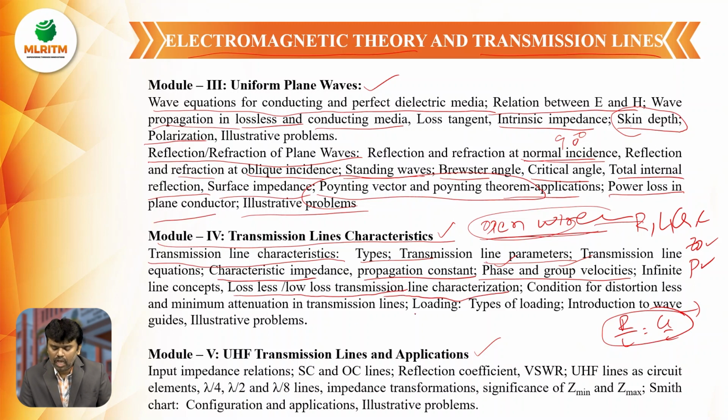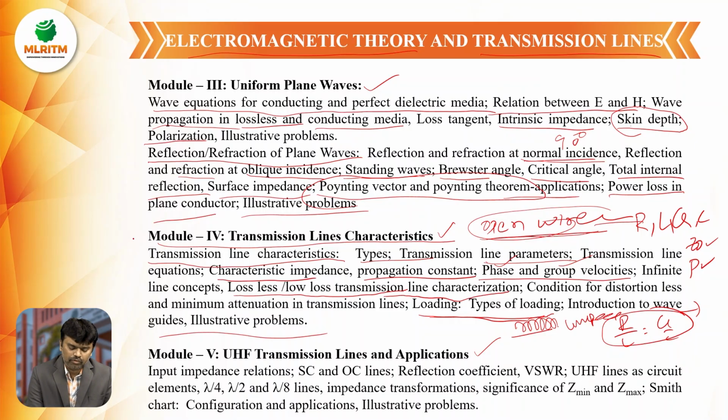How the transmission lines are loaded: loading of lines means applying extra inductors to the transmission lines to get lossless or distortionless transmission. Different types of loading are there. Mainly we use the lumped loading. All these transmission line parameters we will learn in the fourth module.